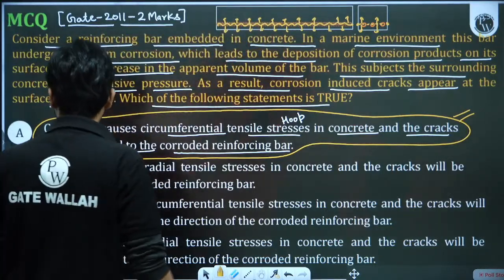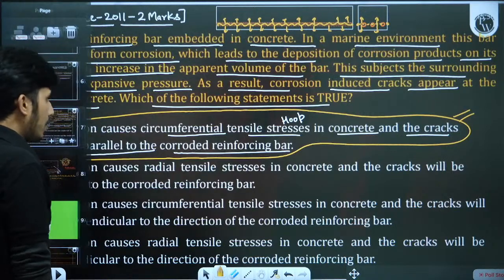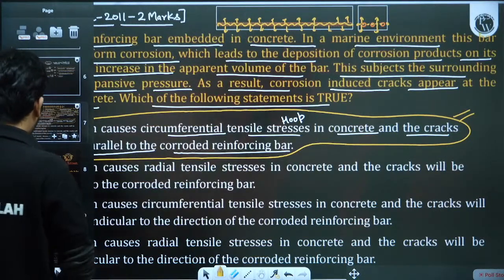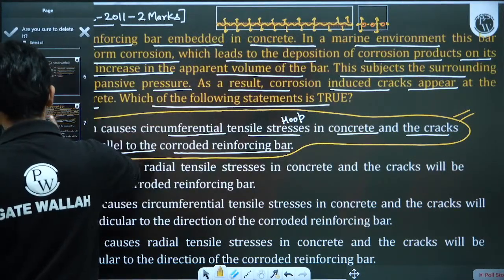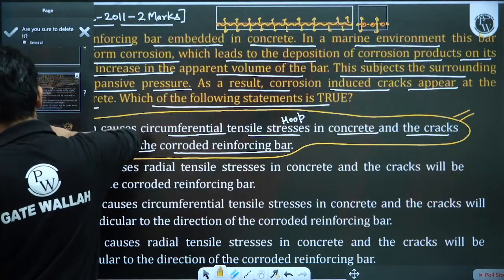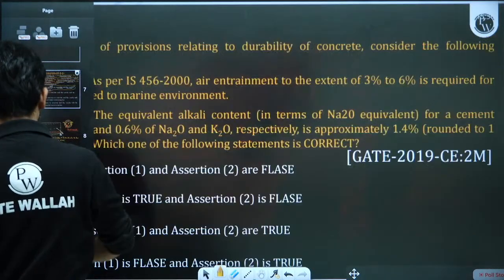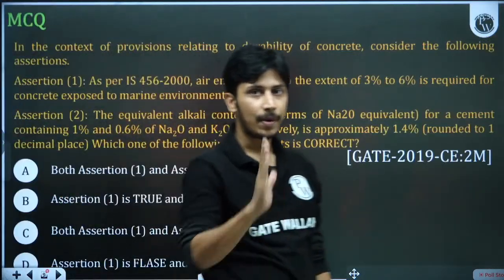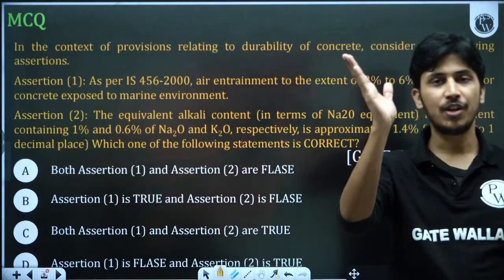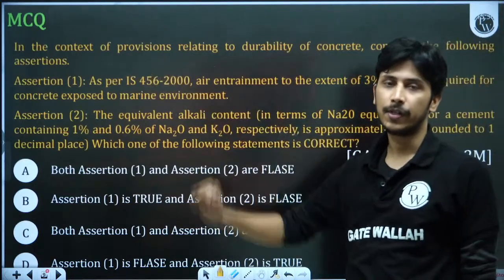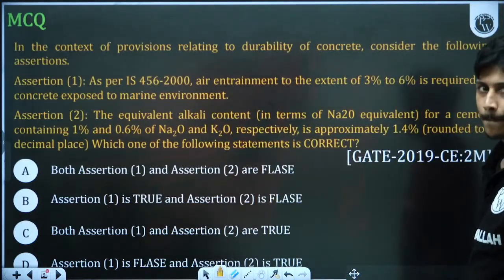Okay. So A part is the correct answer of this. And also remember, you must know the direction of cracks. All the cracks: flexural cracks are perpendicular, inclined cracks are shear cracks, and parallel cracks are corrosion cracks. Because this thing may be asked.